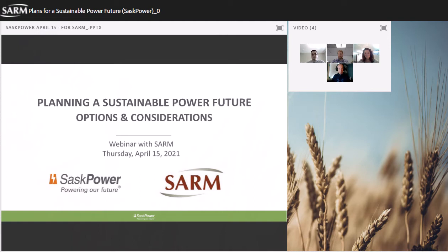There's a lot of regulatory requirements around showing you have emergency services, a workforce that can operate the unit nearby. From a technical perspective, we're going to need a pretty significant water body to cool the steam out of the turbine, and that's typical with our large thermal facilities. So you need that body of water. There are some things that are going to narrow where it's technically possible to do it, and then we're going to evaluate and go from there.